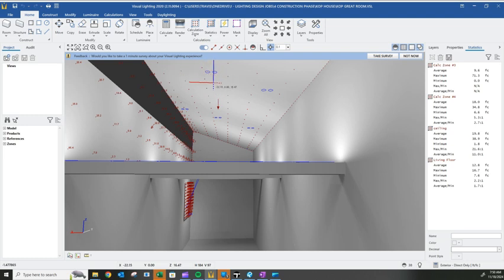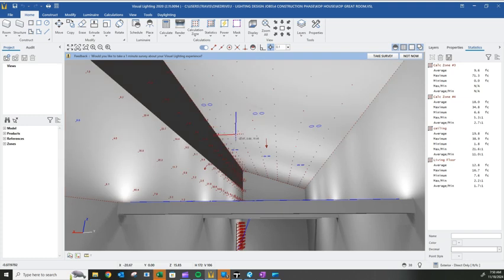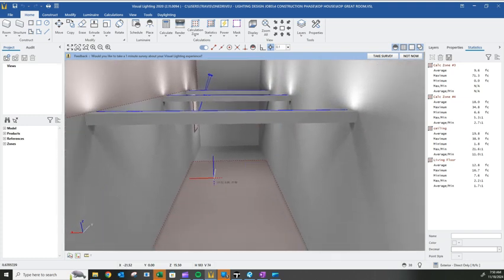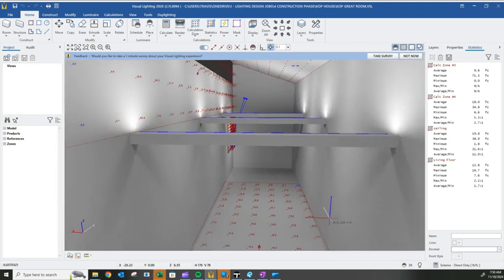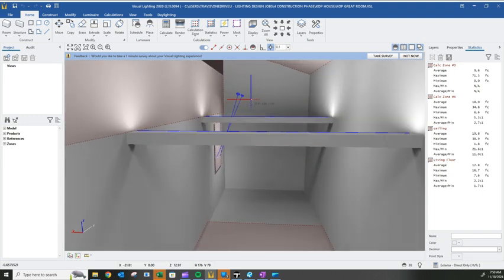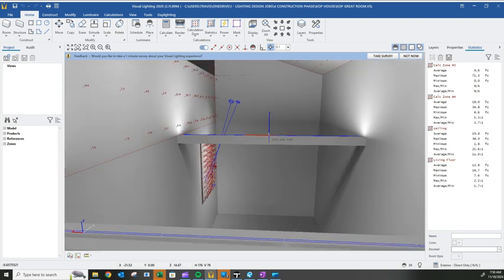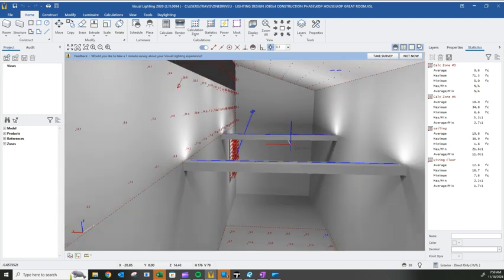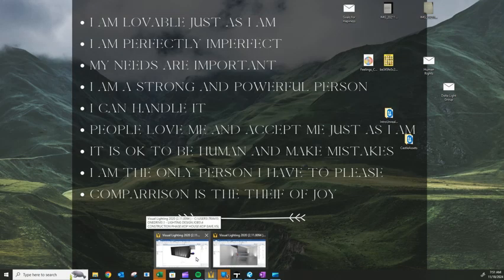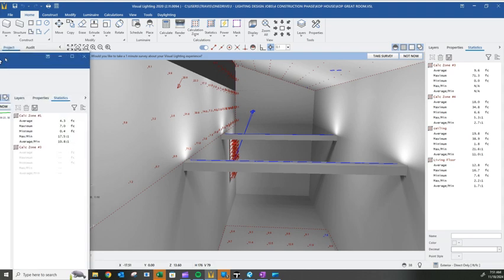So we actually had to do it as recessed multiples, and we picked out a project where we can change out the optics. But I believe this one is like a 40 degree flood to get the light down into the ground. And then here we have shown the IES files for the pendants, where to aim it, and then we have the indirect lights up on the beams. So any areas of concern, we do photometrics on to make sure it's spot on and accurate.